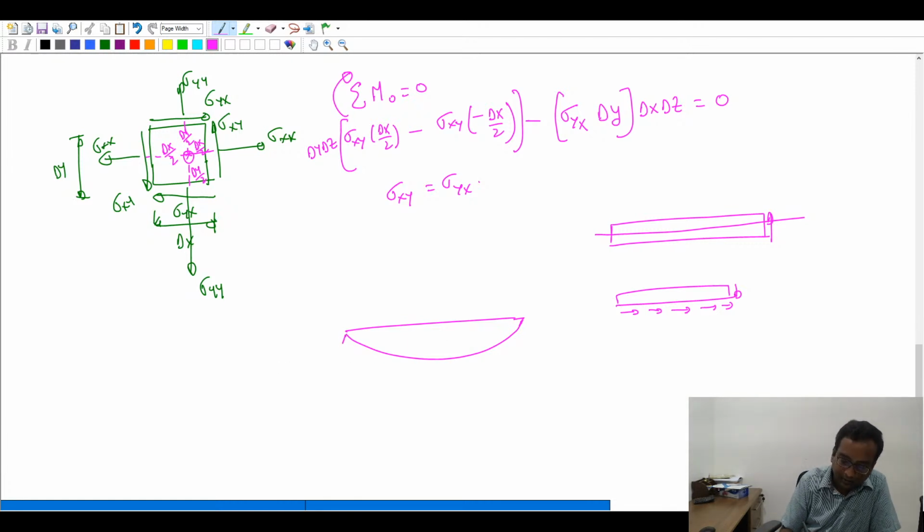That's why we always draw a hinge and a roller here, wherein the roller will move in a bit to accommodate the shortening that the neutral axis has to see, so that it can remain as a zero strain fiber. Okay, so that is the reason why there is no horizontal force on the hinge or a roller.